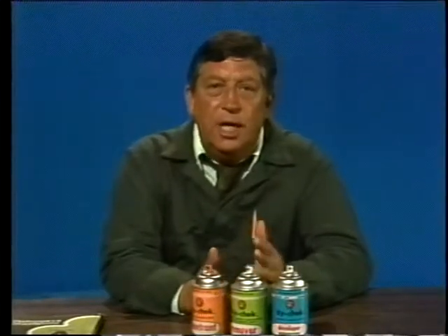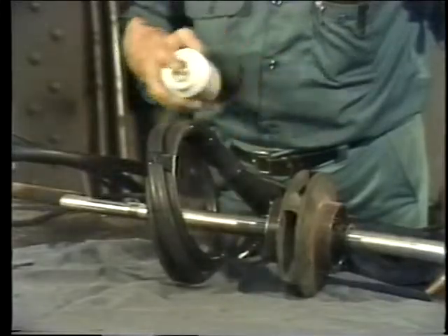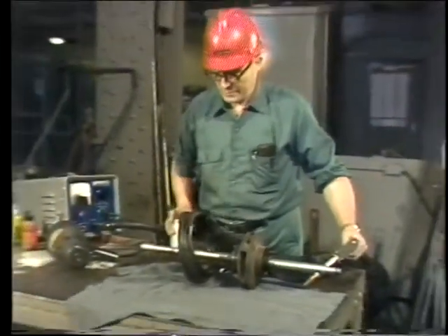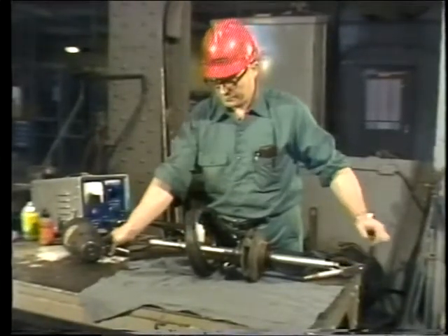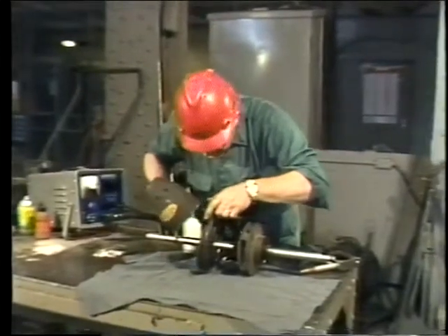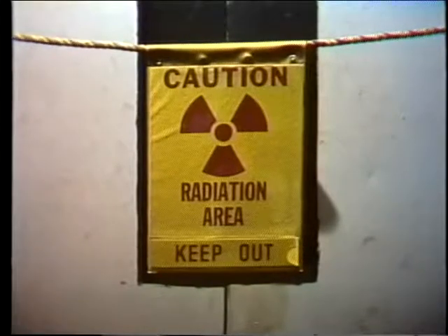Well, you can see that each method of testing has good points and bad. Magnetic particle inspection can only be used on metals that can be magnetized, iron and steel. And the test takes a little while to set up, but it's a quick test for large parts, and it's sensitive enough to detect extremely small defects. Ultrasonic tests can reveal deeply hidden flaws, but they're difficult with irregularly shaped parts, and results are often hard to interpret. Radiographic inspection gives a detailed picture of the inside of a part and requires elaborate safety procedures.